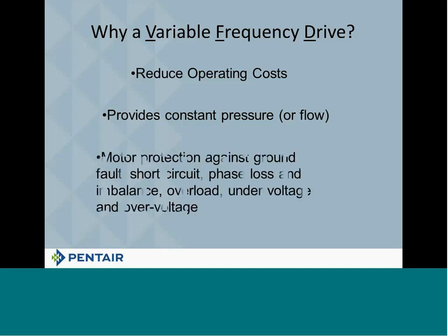We also get motor protection. Now notice what we're protecting against. You're protecting against ground fault. You're protecting against short circuit. You're protecting against phase loss and imbalance. You're protecting against overload. You're protecting against under and over voltage. That's because the drive has all that built into it.